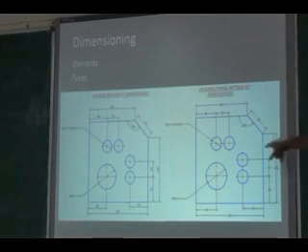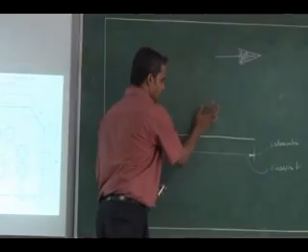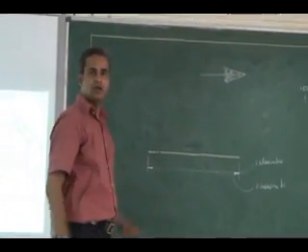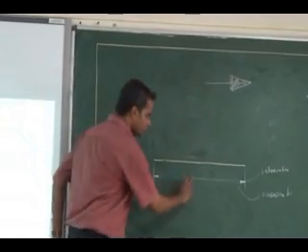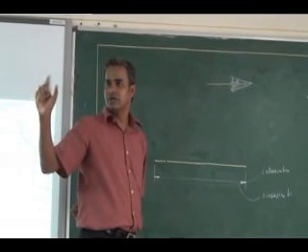So this horizontal system only we are going to follow. Right. Unidirectional method. So here, how can I show the dimension? Here the 100 is the line length. The dimension value you have to show. Where do I have to show it? Over the dimension line, exactly in the middle.